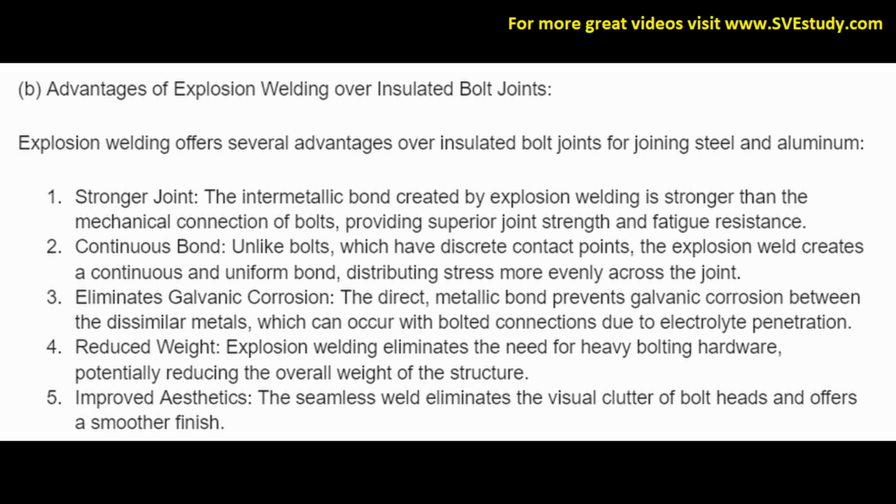B. Advantages of explosion welding over insulated bolt joints. Explosion welding offers several advantages over insulated bolt joints for joining steel and aluminium. 1. Stronger joint. The intermetallic bond created by explosion welding is stronger than the mechanical connection of bolts, providing superior joint strength and fatigue resistance.